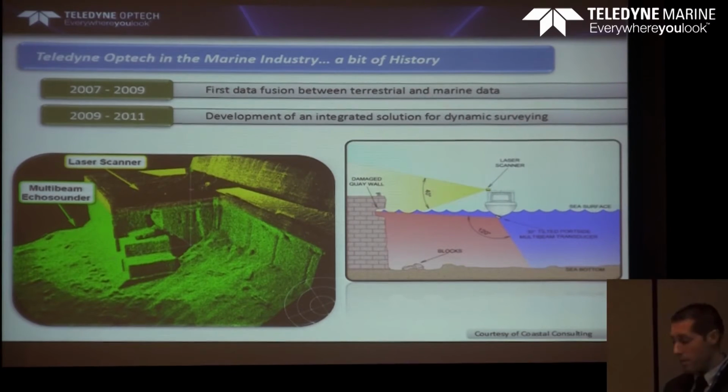So the scanner itself was able to create new, different works. One of the biggest ones was the Quarry Survey. In this case, of course, it completely changed the way of operating the laser scanner with the bathymetry system, the multibeam. It was actually a huge application, the Harbour survey. They use a laser scanner and the bathymetry: the laser scanner scans whatever is over the water, and the bathymetry they usually tilt 30 degrees, and they get all the information on the quay wall.